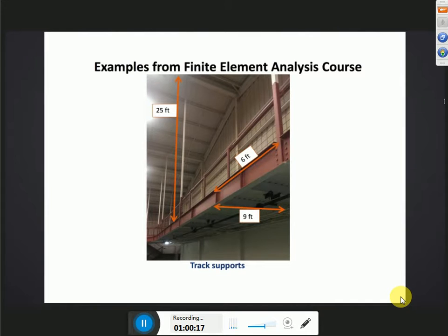Then again, the assembly, how they join, and then of course the safety and societal impact issues. If the rec center is this recreation center, safety is the key, because the load carrying capacity is limited to so many members at a time running on the track, and that's related to vibrations, resonance. How many members can collapse at what frequency becomes a higher level problem. It's not easy to solve, but at least they can solve it in a rough way, a vibration problem that requires a lot of data. And they can explore it.